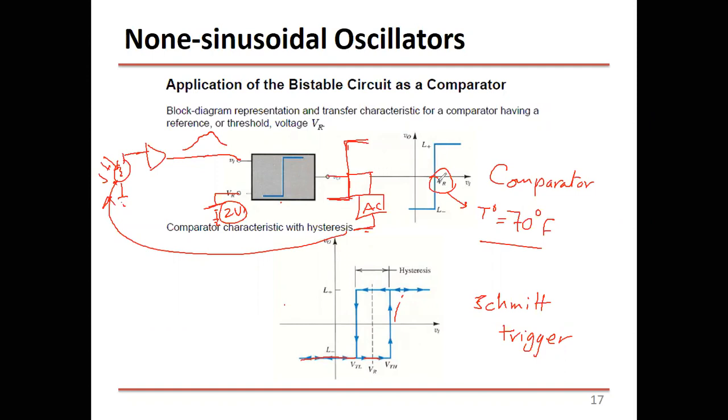So you can see that around the reference, any fluctuation in the room temperature will make this go on and off. So you might hear the contactor or the actuator of the air conditioner going on and off, on and off, on and off, around the room temperature set point. So this is very bad. I'm going to explain next time and continue from this point.